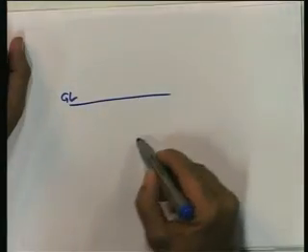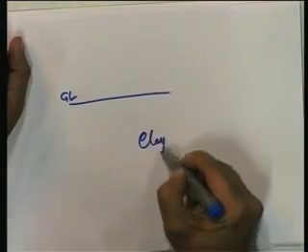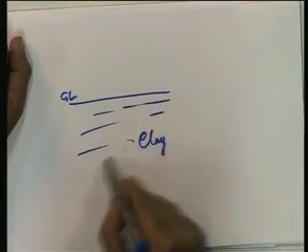To begin with, when there is no structure, when there is soil, it is saturated. There may be pores, but it is saturated, but it is under hydrostatic state, and there will be no flow of water, and it will be in full equilibrium. What I mean by that is, suppose there is this ground level, this is this clay layer, and it is completely saturated.